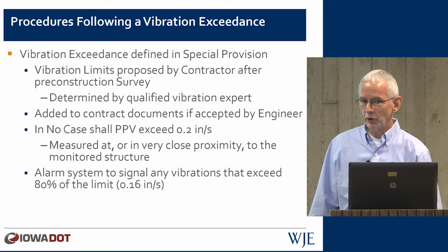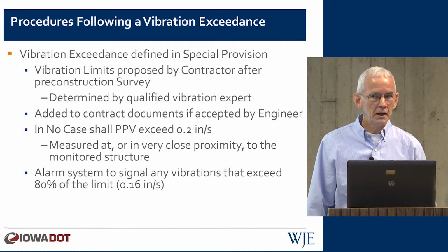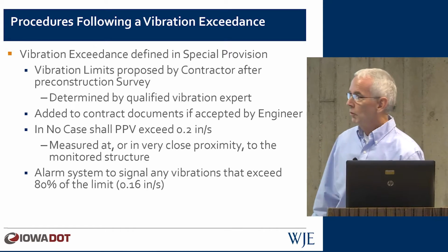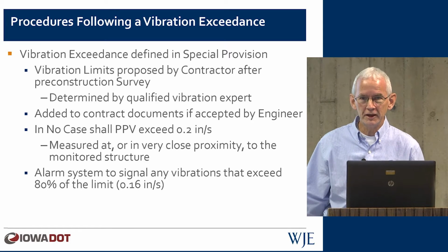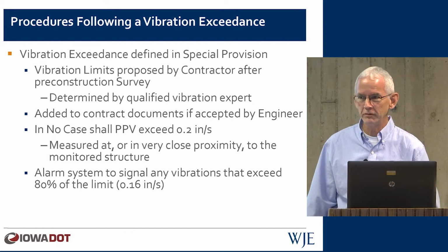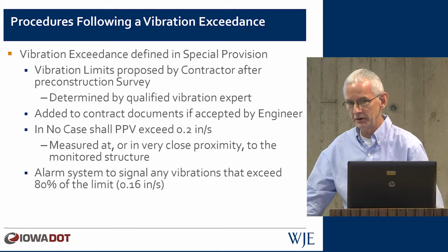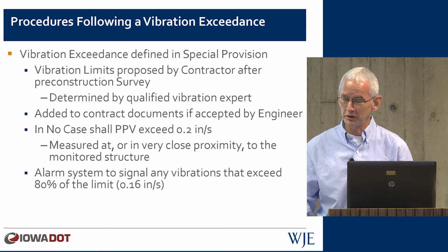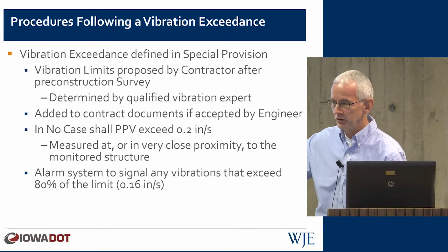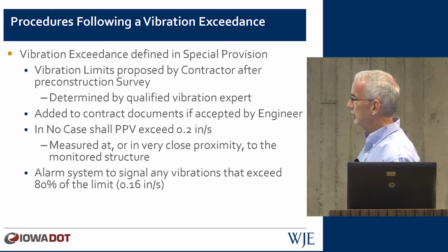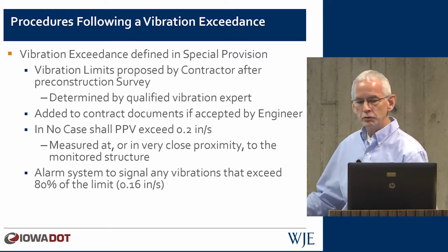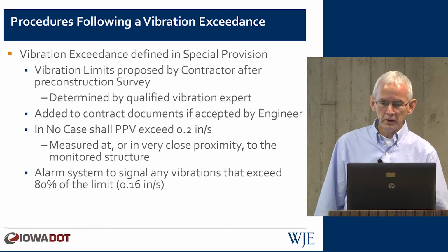But we also point out that any frequency that's greater than 100 hertz has a very low likelihood of causing any kind of damage to a structure, because that's usually a much more localized vibration event. It's something like somebody dropping a hammer on the floor next to the transducer. That is going to produce a high frequency spike of vibration, but it's not enough energy to transmit throughout the structure and shake a wall enough to crack it. So each triggered event has to get reviewed.